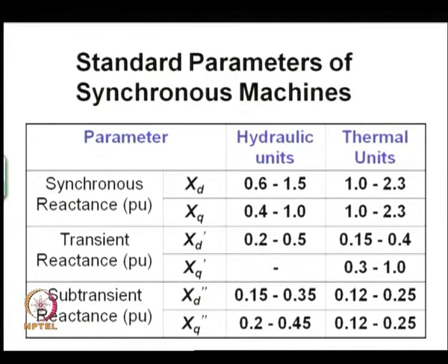The reason is that synchronous machines which are driven by hydraulic turbines, normally salient pole machines, can be represented very well by just one damper winding on the q axis, because of which we need not. So, your transfer function, psi qs upon I qs, is only of first order.